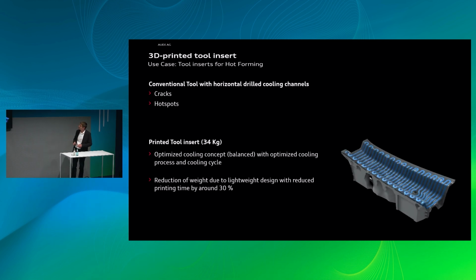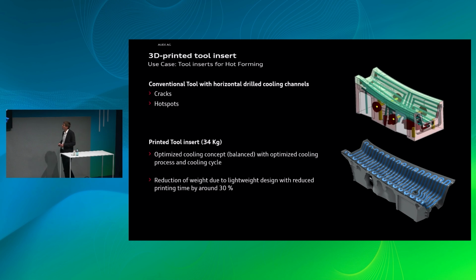Okay, there are some pictures here. We are coming from a conventionally cooled segment with horizontally drilled cooling channels, and the temperature on the surface differs because of the different distance to the mold surface or die surface.